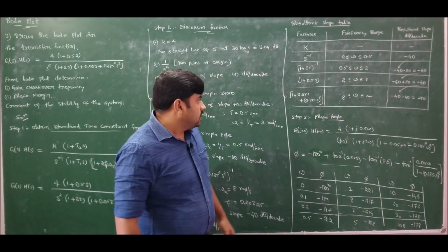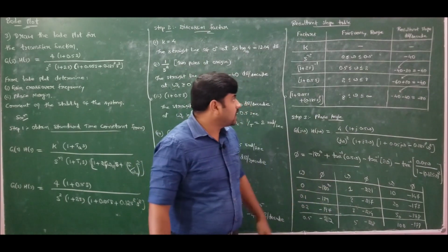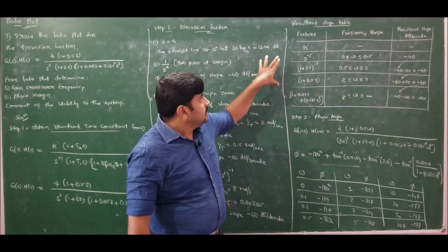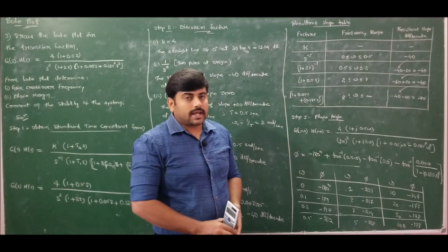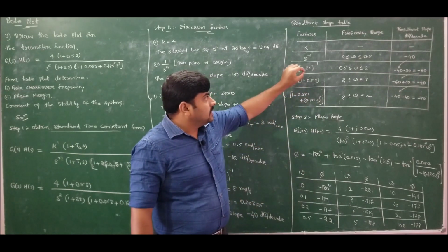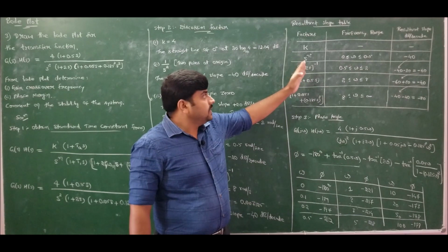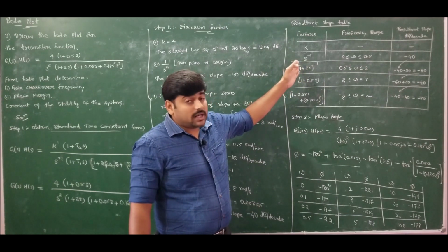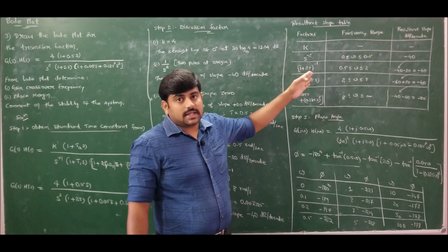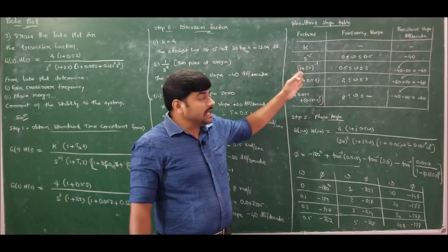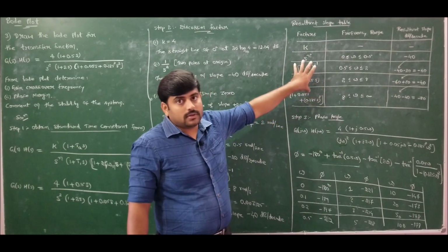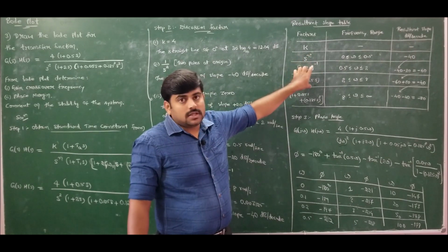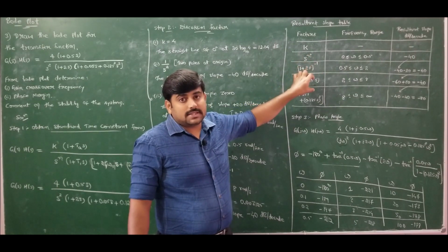So we have obtained the phase angles to plot, and also the resultant plot, the slopes of the straight lines. If I put it in the Bode plot, I can determine at what frequency the magnitude plot is crossing the 0 reference line. That will give us the gain crossover frequency, the frequency at which the magnitude plot attains a magnitude of 0 decibels.